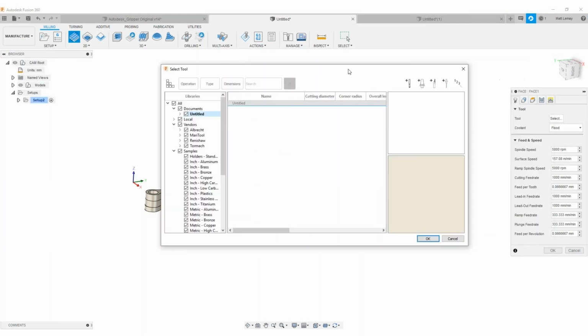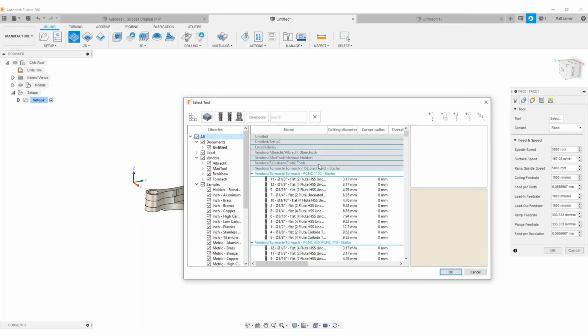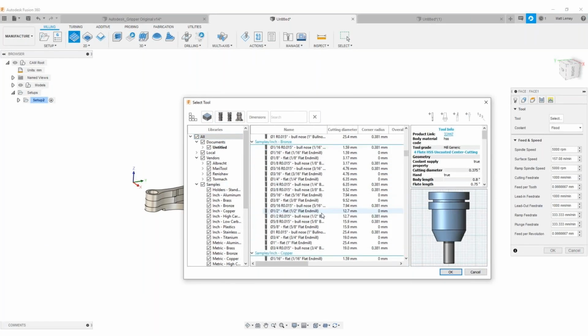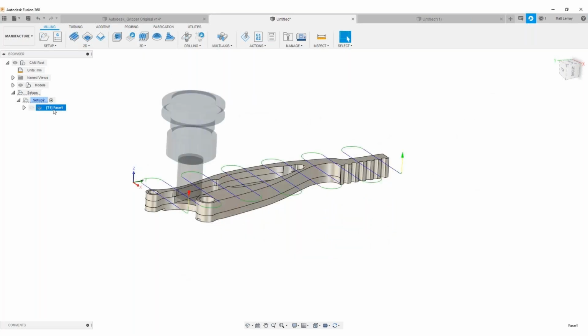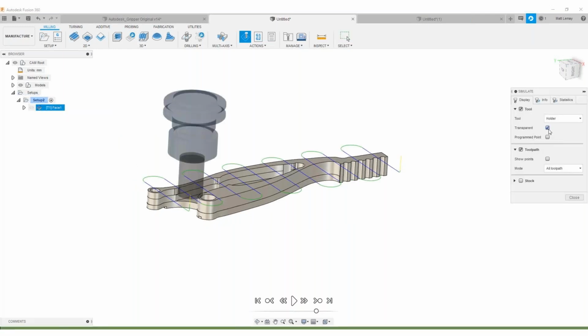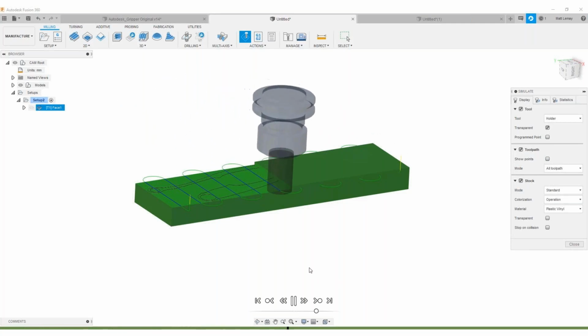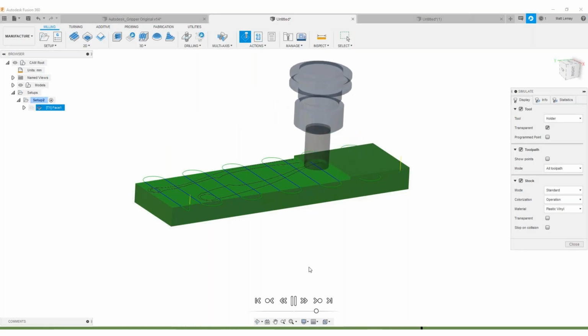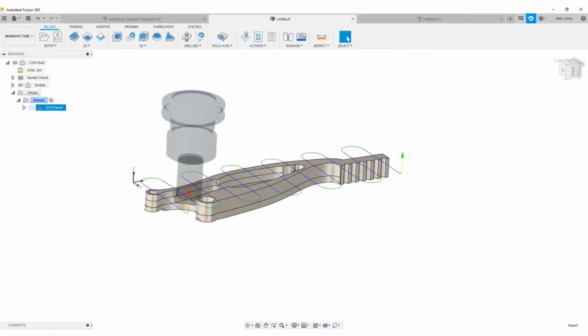And then, as I was saying, I can bring back those components in Inventor and modify them there, even if in Fusion 360 we have some specific tools for doing that, like the T-spline for the organic shape. But for instance, I also have the option in Fusion 360 to generate the toolpath for the 2.5 axis outcome, and then generate and export the relative G-code. So I can simulate.